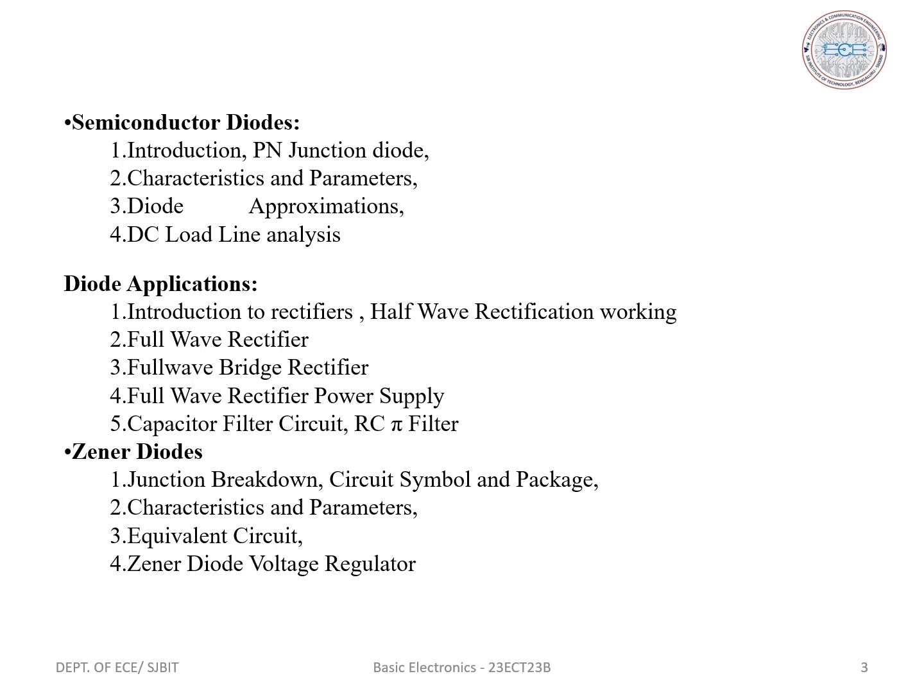After the formation of the PN junction, when no external voltage is applied, the free electrons from the N side will diffuse into the P side and recombine with the holes present there. Each electron diffusing into the P side will leave behind a positive immobile ion on the N side.